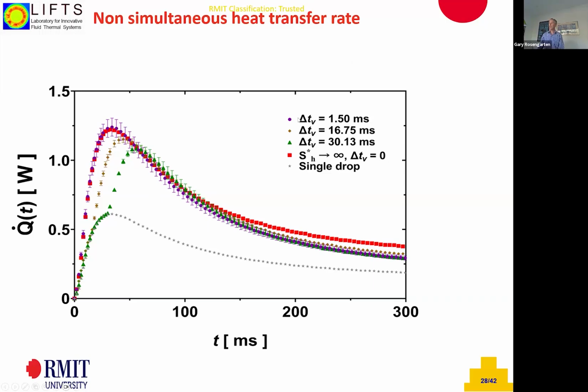Nothing else. When they were interacting, it was close when they were spreading, but it didn't even get to the non-interacting droplets at all. So that tells a story that you don't really want them interacting, because that interacting starts to mix up the cooler fluid with the hot fluid and take some of that energy out.